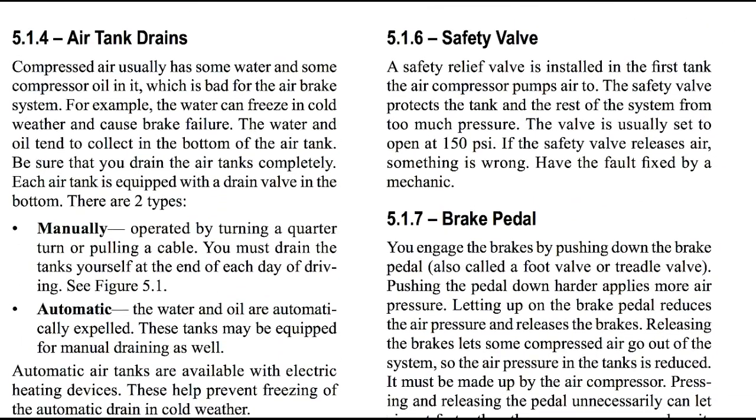Safety valve. A safety relief valve is installed in the first tank the air compressor pumps air into. The safety valve protects the tank and the rest of the system from too much pressure. The valve is usually set to open at 150 psi. If the safety valve releases air, something is wrong. Have the fault fixed by a mechanic.